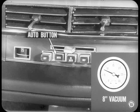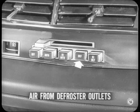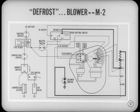That's right, Jack. Now, to check out the defroster buttons, you have to again return to the auto button position. So push the auto button and set the tester vacuum dial so the gauge reads 8 inches. Pushing the defrost button doesn't change the vacuum reading, but the air conditioning outlets will be closed off. All of the air will be coming out of the defroster outlets except for the normal 20% bleed through the heater doors. The output air temperature will be the same as in the auto position, but the blower speed will be in M2. That's because the current from the push button goes through only 2 resistors in the resistor block.